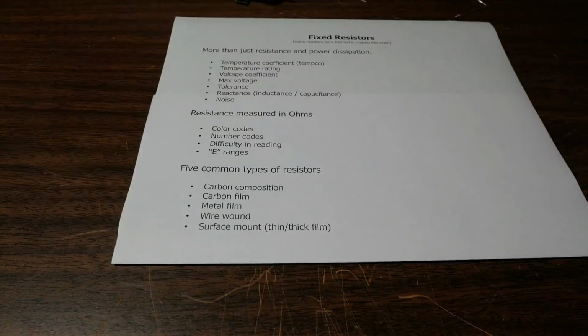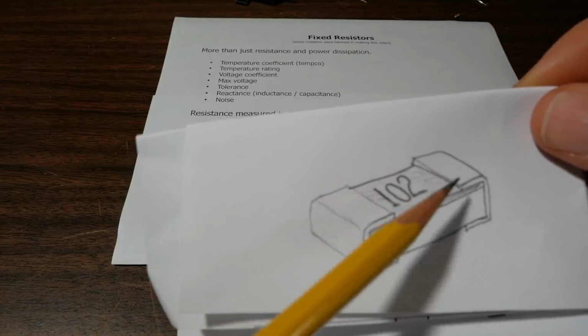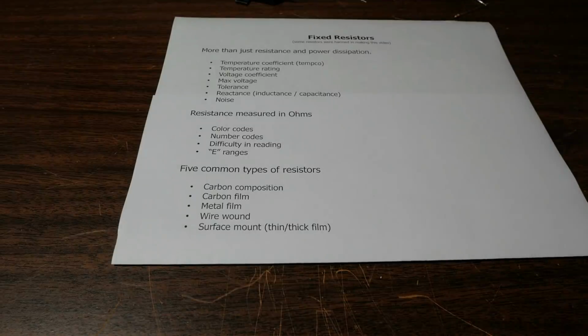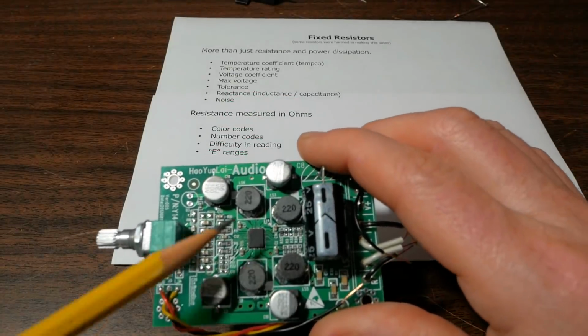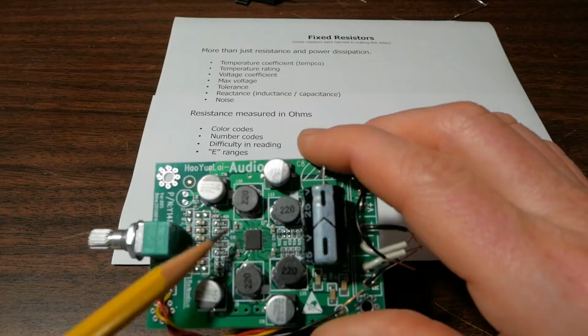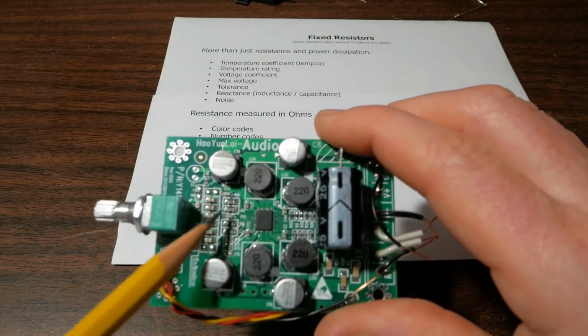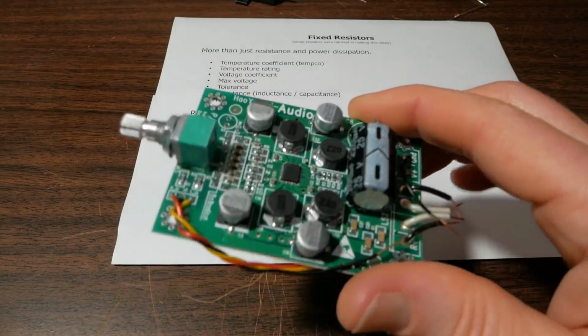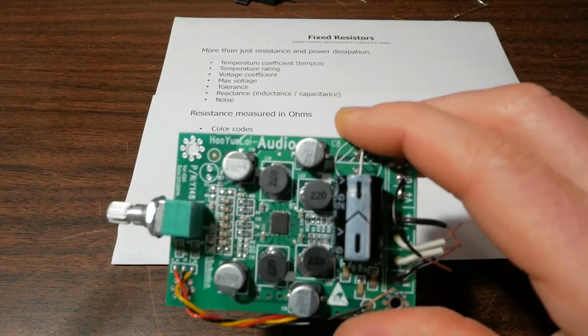Surface mount resistors have very good performance. They can be high precision, they're low noise, and because there's not a coil of the resistive material, there's not a big issue with inductance. And of course they can have a very small form factor. They can also use copper foil areas to help dissipate heat. Of course higher power ones are going to be larger in size, but yeah, they're very space efficient, not having those leads to deal with.